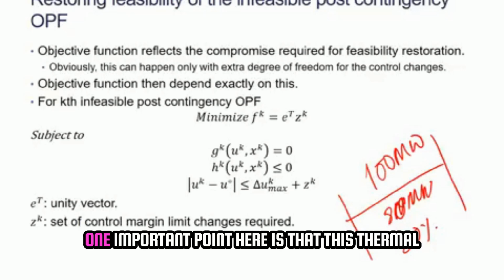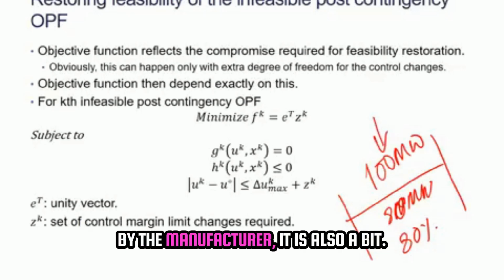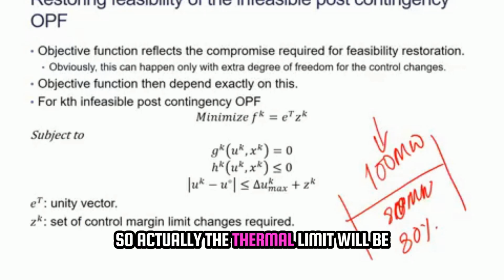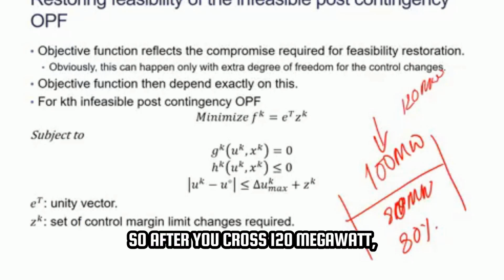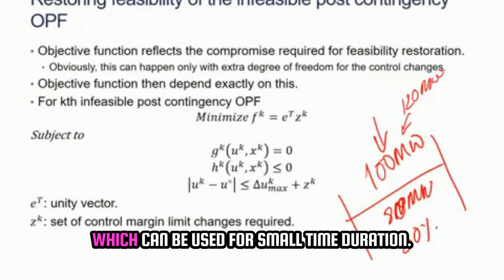Also, one important point here is that this thermal limit, generally what is given by the manufacturer, is also a bit, basically as a manufacturer, he also ensures some margin. So actually the thermal limit will be somewhere around 120 or even more. After you cross 120 megawatt, then the wires will start melting. So they actually keep some margin here also, which can be used for small time duration.